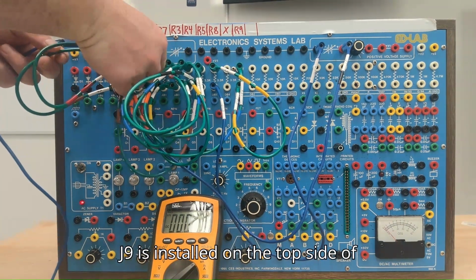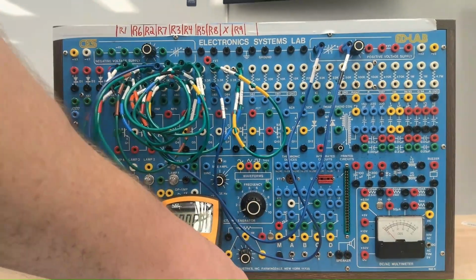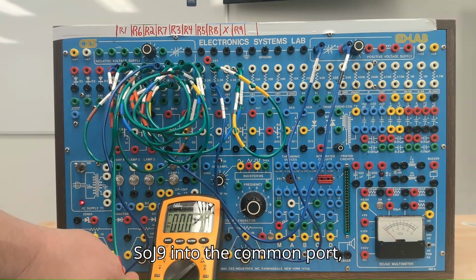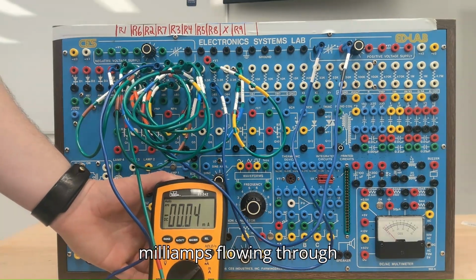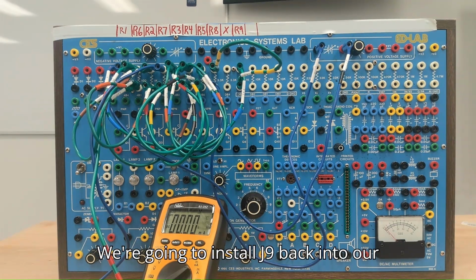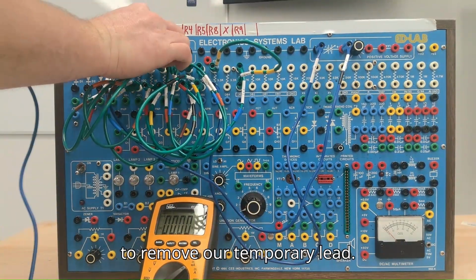J9 is installed on the top side of R7. We're going to install our temporary lead in the top side of R7 and put this into our meter. So J9 into the common port, and we have 0.04 milliamps flowing through J9. We're going to install J9 back into our circuit. J9 was installed on the top of R7. We're going to remove our temporary lead,